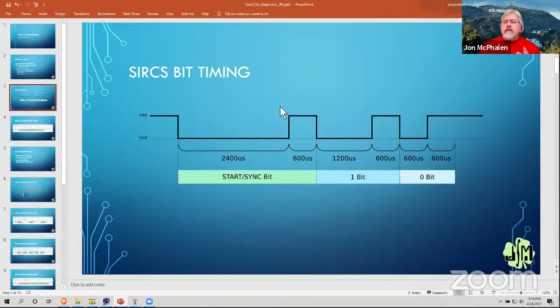And so we need the Propeller to talk S-Bus as well, because we also have the ability to control the lens. So the Ronin is only controlling what the camera is looking at. John and I have also developed lens control, so we can control focus and zoom. So we'll have S-Bus output to the Ronin to control where the camera is pointed and how it's configured. And then we'll have focus and zoom controls as well for the lens. So just like with today, where we did receive and transmit, we will do that also with the S-Bus. We want to have both sides of the equation.